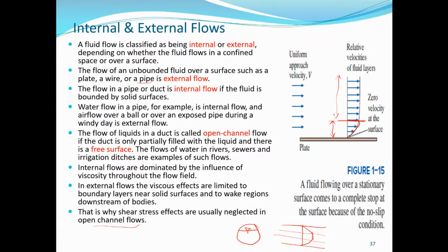It is treated as open channel flow, and this is usually the flow in sewers. Sewers are the pipes that convey the wastewater from our residential areas to the wastewater treatment plant. Sewers do not flow full, but pipes meant for water supply, they flow full. And those that do not flow full, or open channel, in which the flow is in channels, in canals, in streams and rivers, they are all open channel flows.